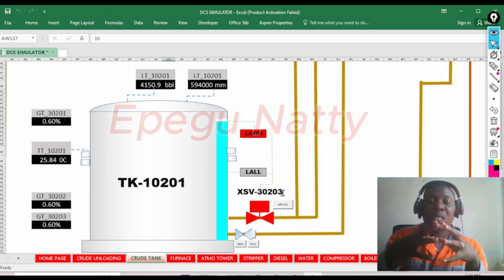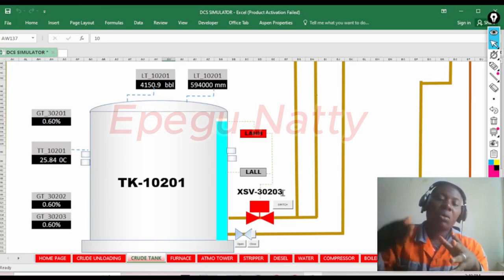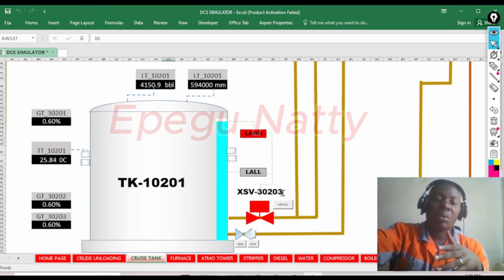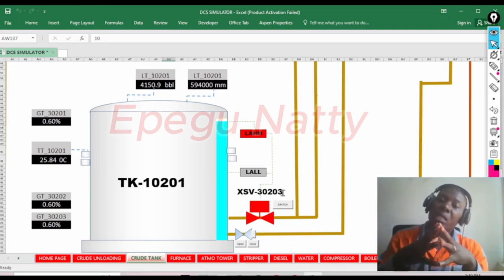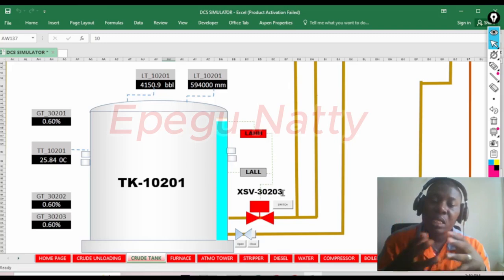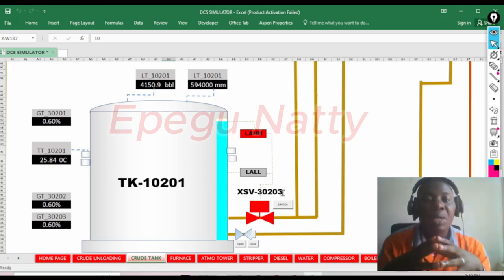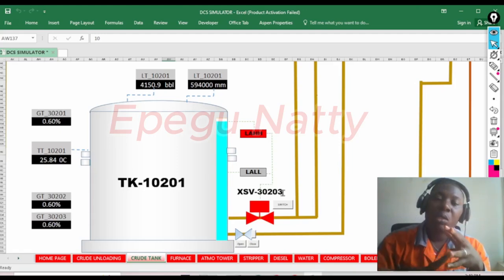So you need to look at the system design also, because like I mentioned, what if the interlock is from the gas detector and not from the trip, right? The next is we evaluate the safety integrity. The safety integrity is the SIL rating, C1, C2, C3.